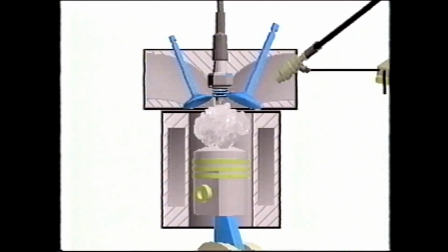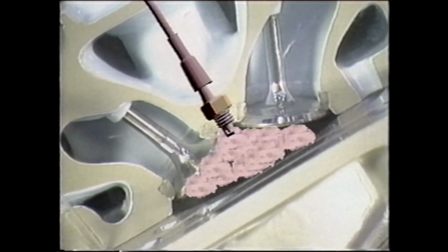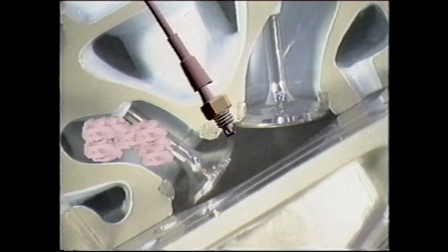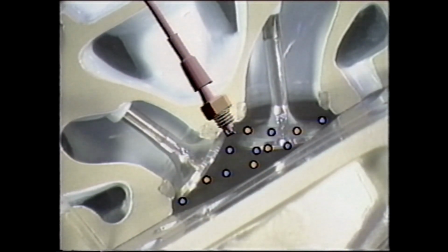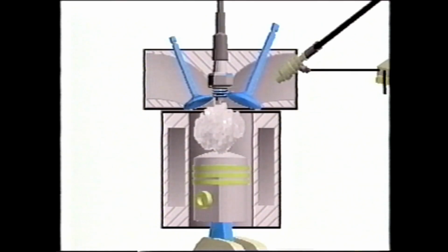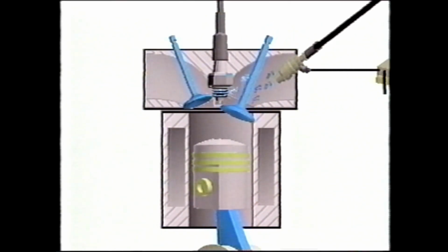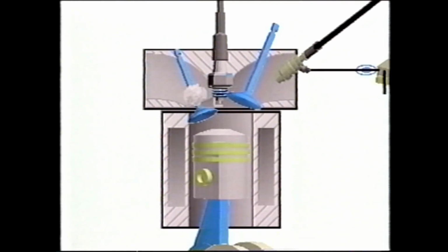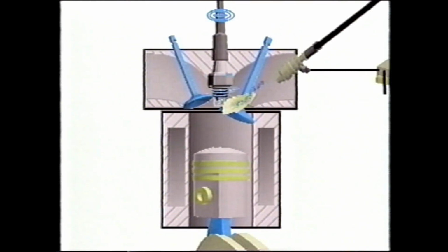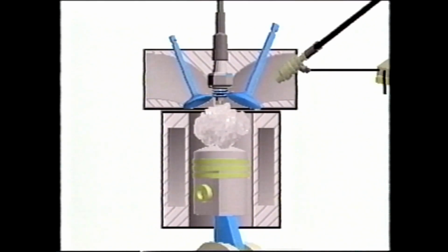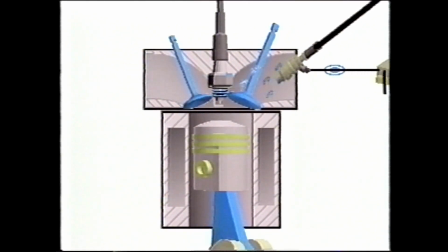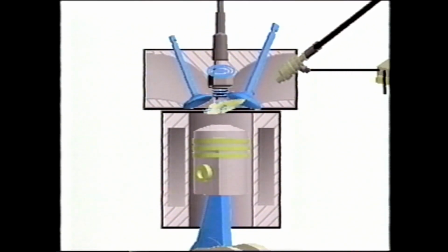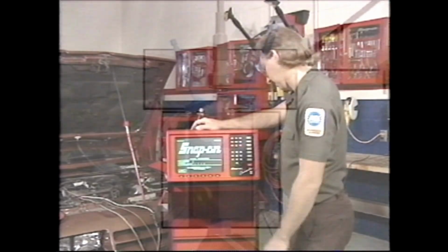As the piston nears the bottom, the exhaust valve opens, releasing remaining gases and decreasing the pressure even more. The piston moves upward on the exhaust stroke, pushing remaining fumes out of the cylinder. Before the piston reaches the top, the intake valve opens. When the piston passes the top, the exhaust valve closes and the cycle repeats.